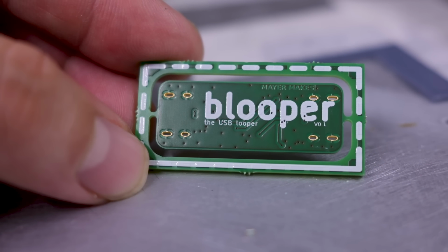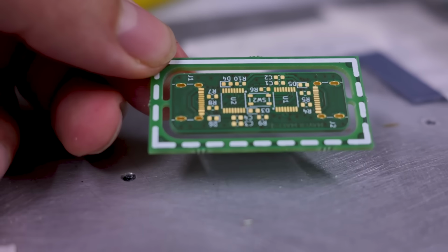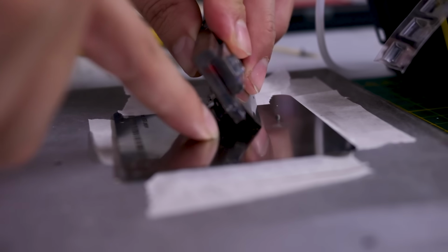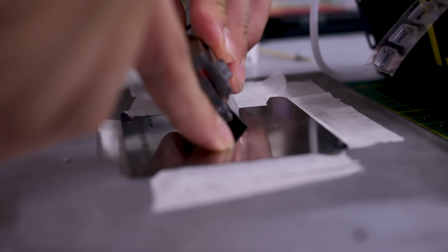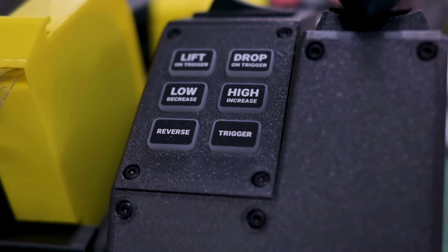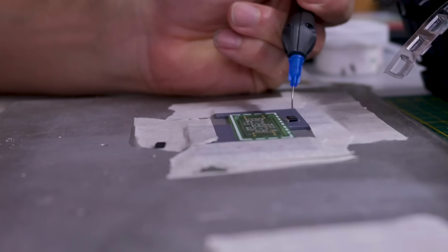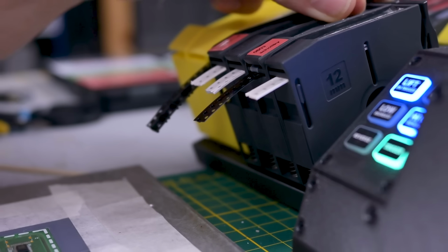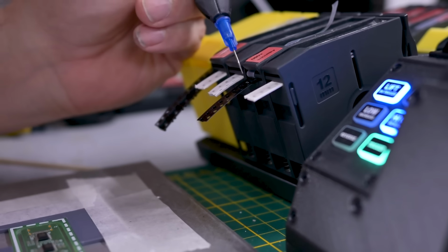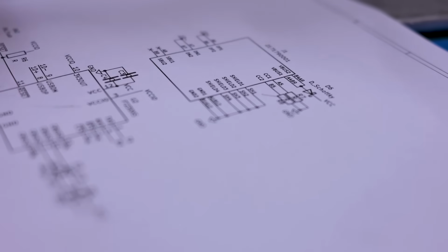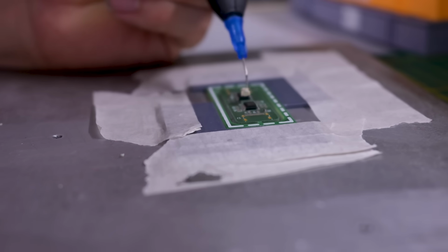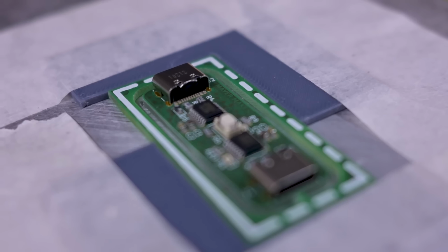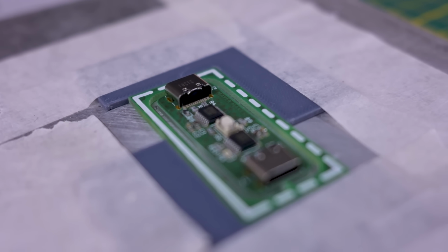Assembly of the Blooper might be a bit fiddly because you have a lot of small components. I only need 2 LEDs, even though there are 4 input-output LED indicators, because they're both joined together, so I just use 2 differently colored LEDs to show which one currently issues traffic. That's all I need. A handful of passives, the UART to USB chips, of course, some USB-C ports, and I assembled the whole thing with my trusty pixel pump, which comes in as a godsend for these little fiddly jobs.